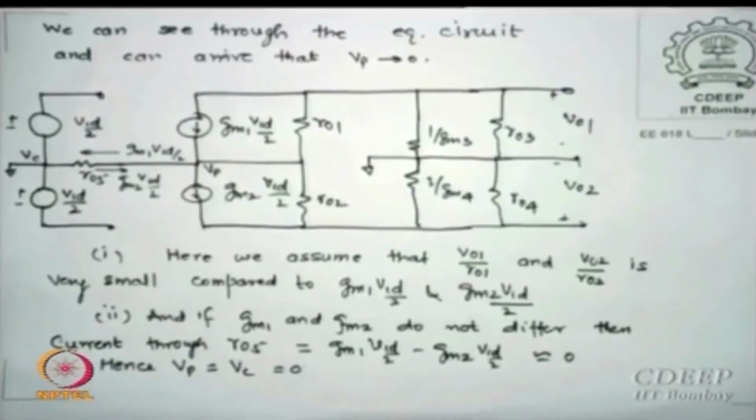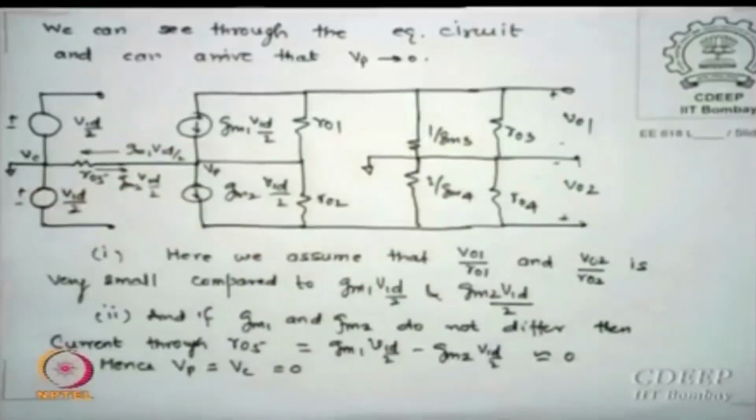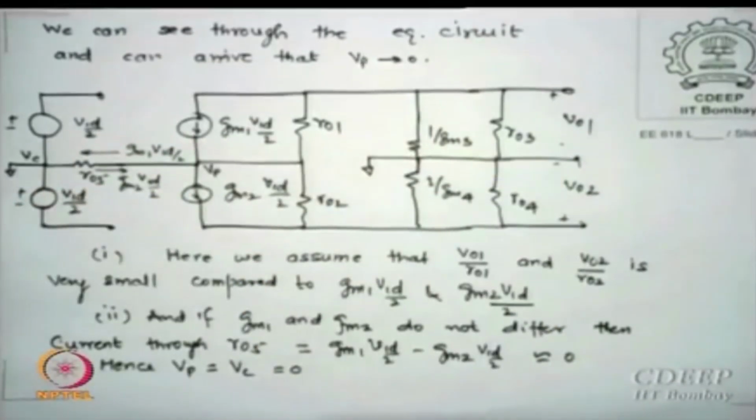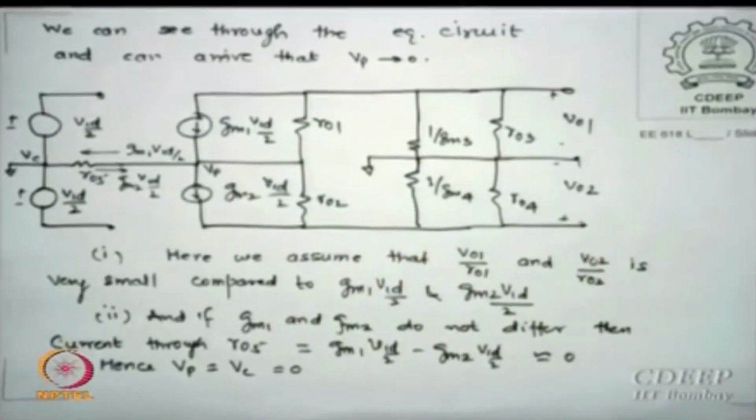Is that clear? So that delta Vp does not move by lemma is what I have used, but I now showed you through a circuit point of view that Vp remains constant, so no AC current, that voltage for AC is same as Vc. So this idea, in circuits, how people use that, sometimes because they may not show you this, they may suddenly put a ground there. So you must know from where this theory has come, that Vp can be treated for AC as ground.